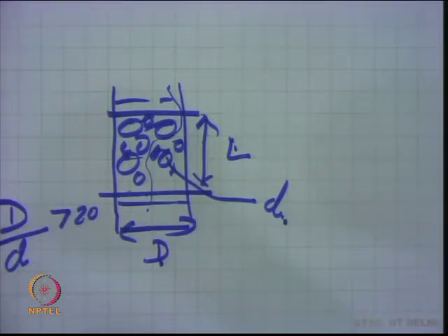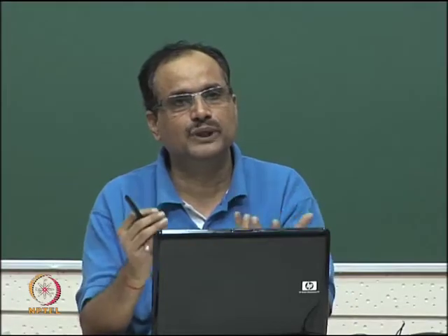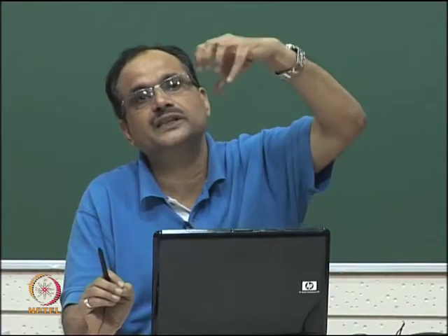So, this is one. The same thing can be done in a fluidized bed reactor also. Fluidized bed means something where the solid is acting like a fluid. These are small particles which are fluidized in a fluid medium or bubbling medium in the presence of some gas. So, some carrier gas may be required to keep the particles in suspension.